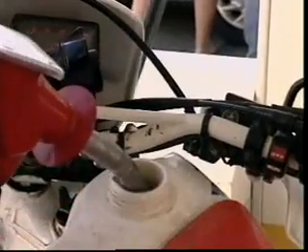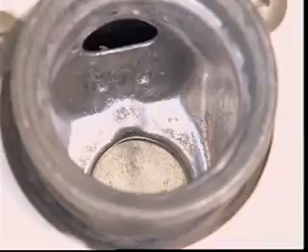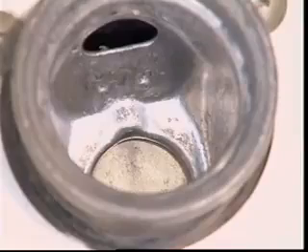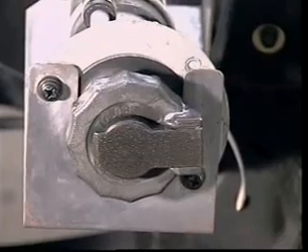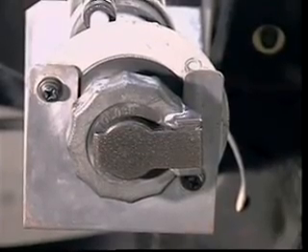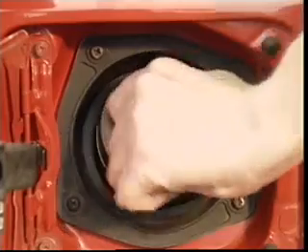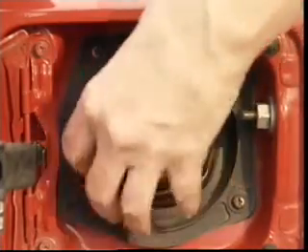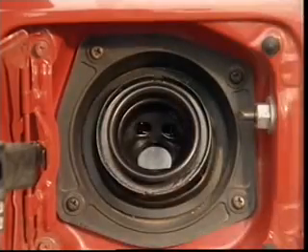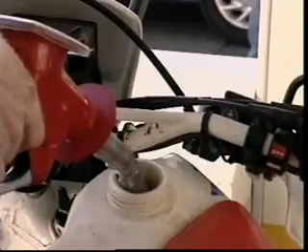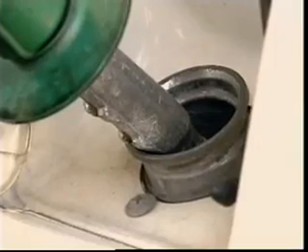Its diameter is smaller than those on leaded vehicles, and a trapdoor inside the filler can only be opened by the nozzle of the unleaded petrol spout. The filler cap seals the filler neck to keep out water and foreign objects. Water can corrode internal passages of fuel pumps and carburetors. The cap on the petrol tank also stops petrol vapour escaping and polluting the atmosphere. This is important for petrol, which is very volatile and vaporizes easily, especially in warmer climates.